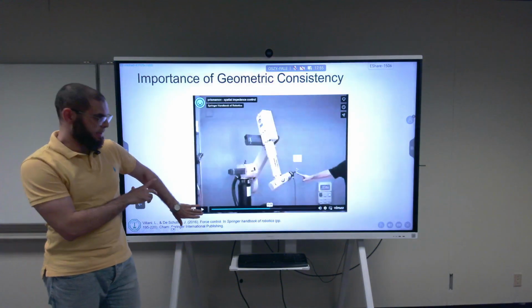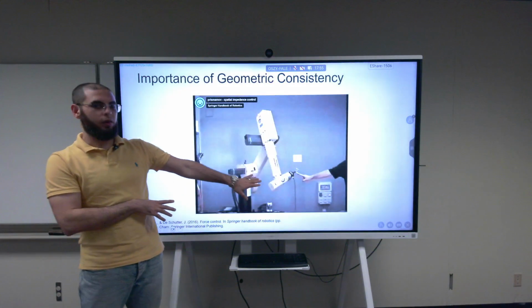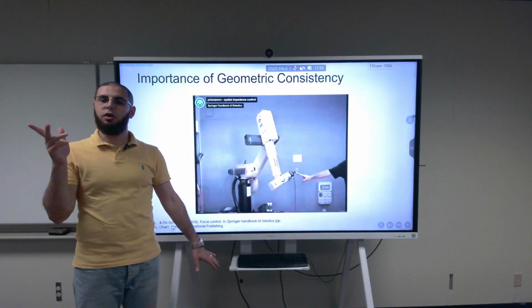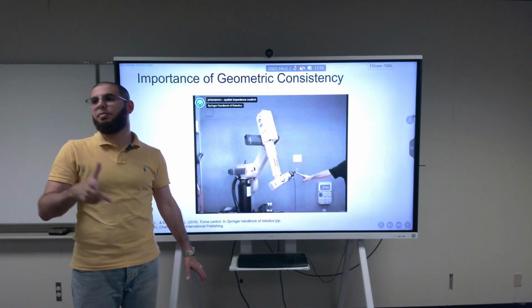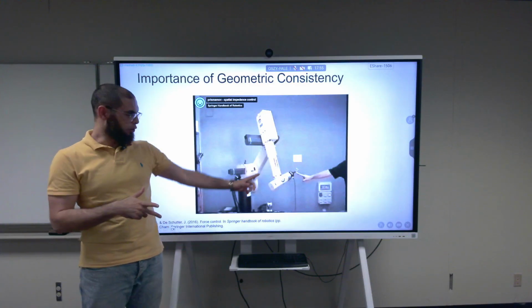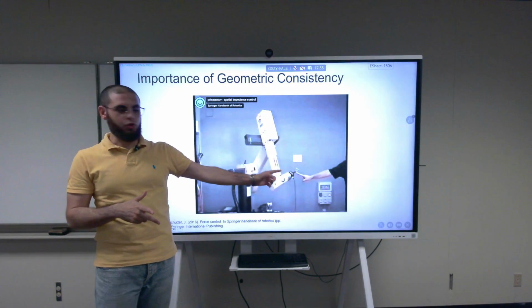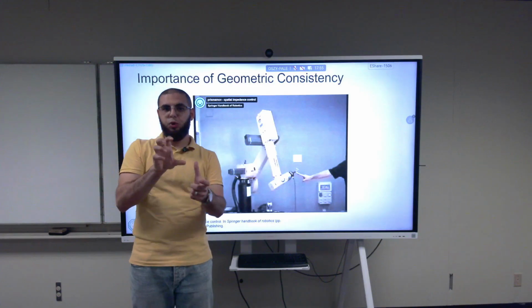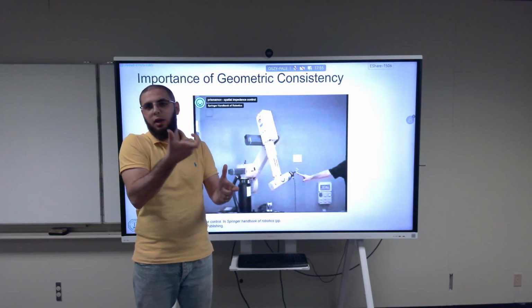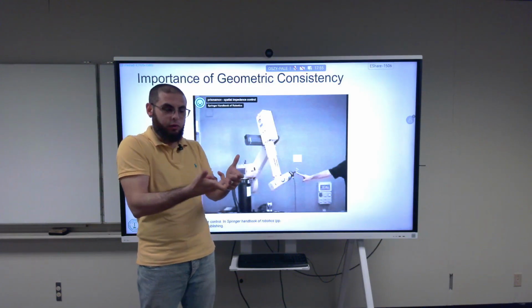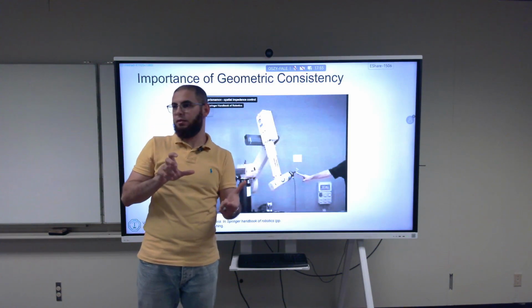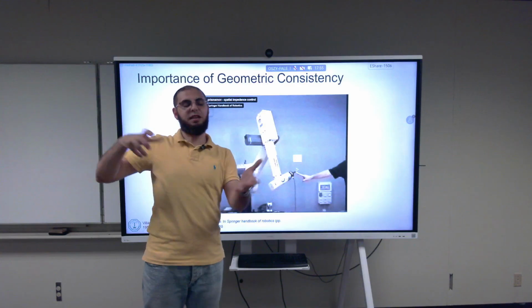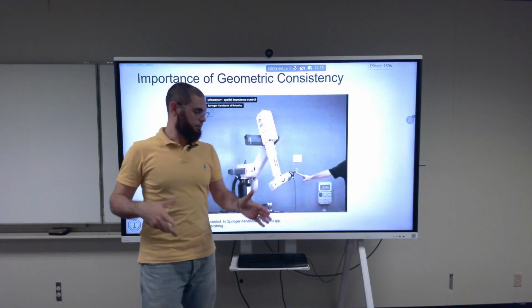So now pay attention, okay? What you'll see right now is the Euler angle based impedance control, okay? And take a look at the behavior of the end effector. So what he'll do is rotate it by hand. He's going to put an interaction torque around one axis and take a look at how the robot goes back when he removes his hand. Because when he removes his hand, it means that there is no interaction now.